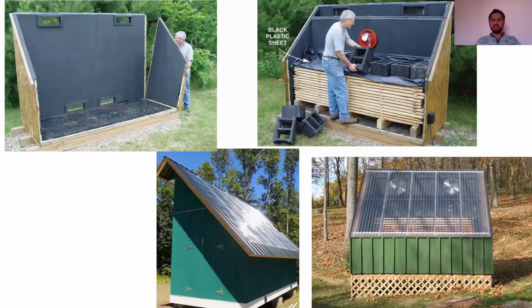At the top, you can see a single window of the same thickness, from which the heat is absorbed, and it will be transported to the inside part, in which the timber will be kept, and the air will be circulated. As the heat is taken from the solar, the heat goes inside, and the air will be passed. The air will become hot, and it will be circulated among the timber, and the timber will get seasoned. It will take twice the time of the previous one, that is kiln seasoning.